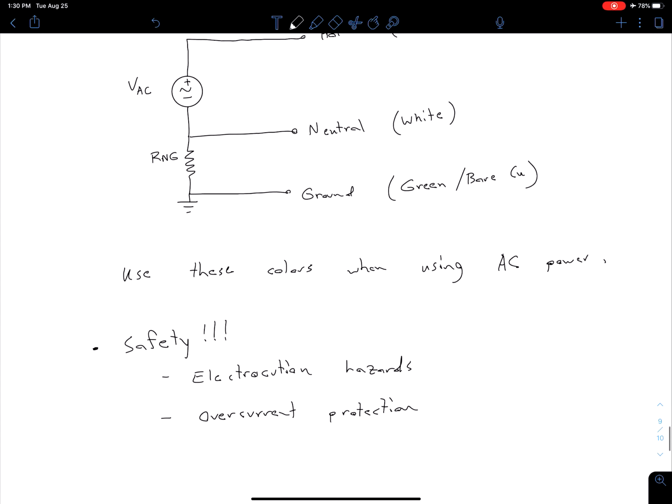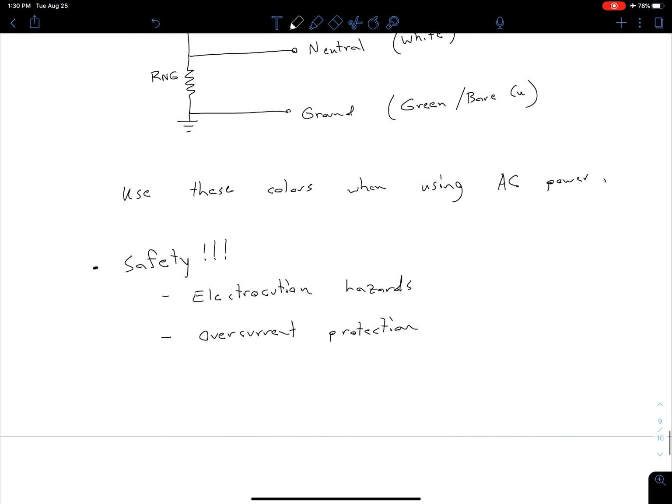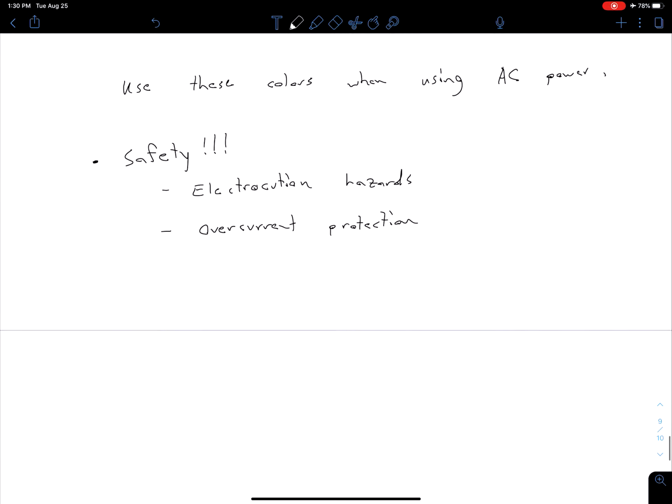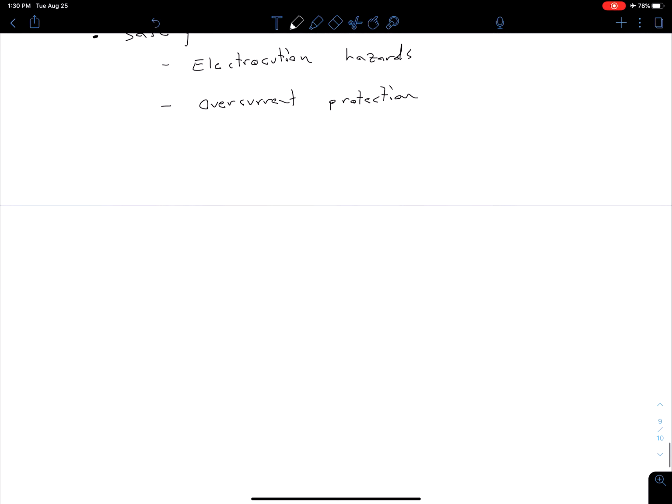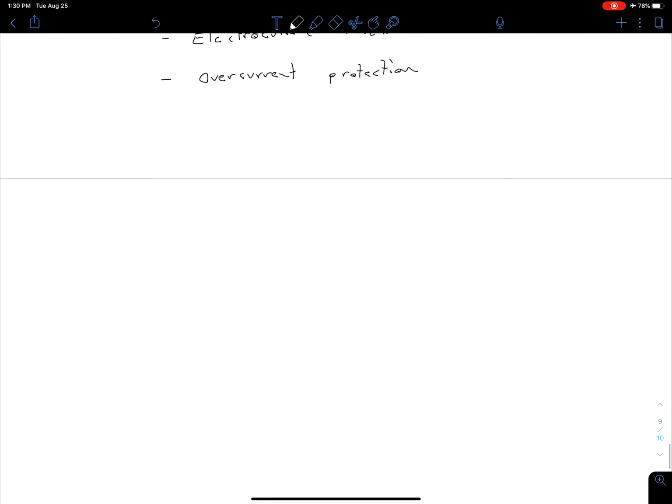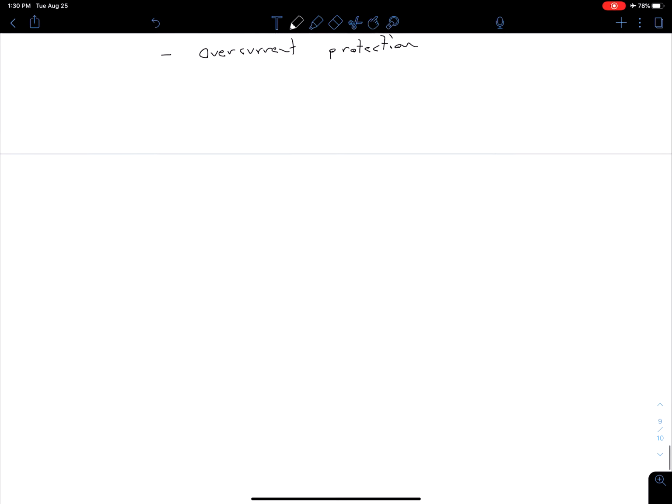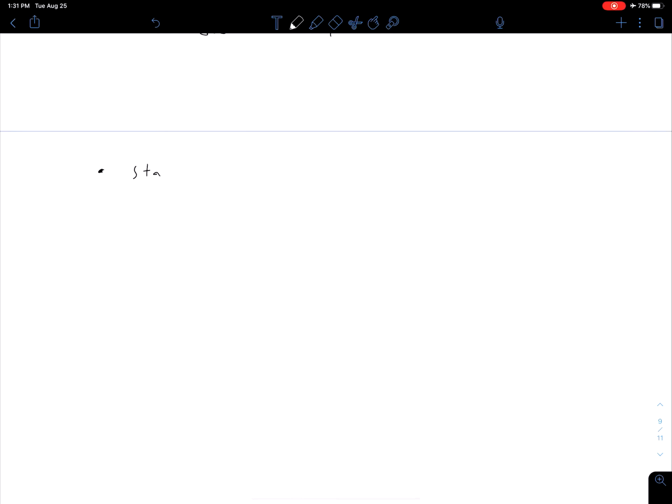Here we've talked about the single phase service, but like I said, power, at least in the US, is primarily transmitted with three-phase AC. There are some appliances in homes and of course a lot of things in industrial spaces that will use three-phase power. Typically we're going to do that when our standalone load is using more than about 2 to 5 kilowatts. So standalone loads greater than about 2 to 5 kilowatts means that we're going to use three-phase power.